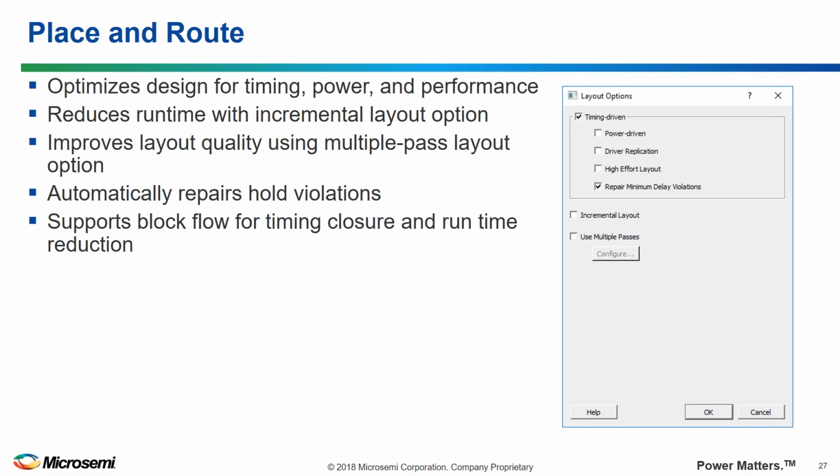You can use the Chip Planner tool to do floor planning. You can make all of your constraints, your physical constraints, your timing constraints, and so on. And then we get to the point where we push the button and let the tool do all the place and route. That's going to take all the cells in our netlist and put them somewhere on the die. It's going to make all of the routing interconnects. Now we have some options that we can use for layout.